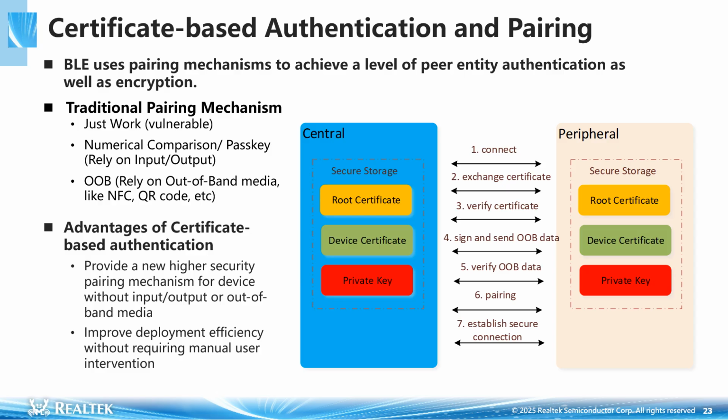Next, let's look at the advantages of using certificate-based authentication for BLE pairing. Higher security level. Certificate-based authentication offers a higher security level for pairing, especially for devices without input-output or out-of-band media, by using certificates for authentication.